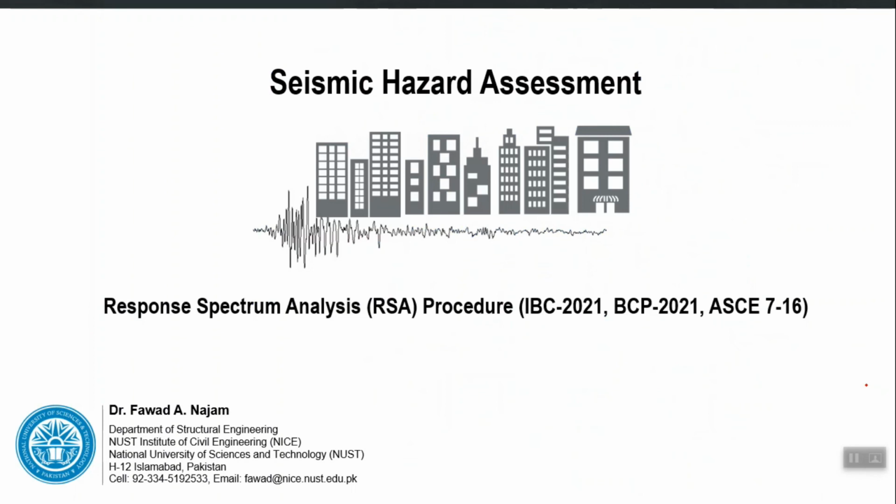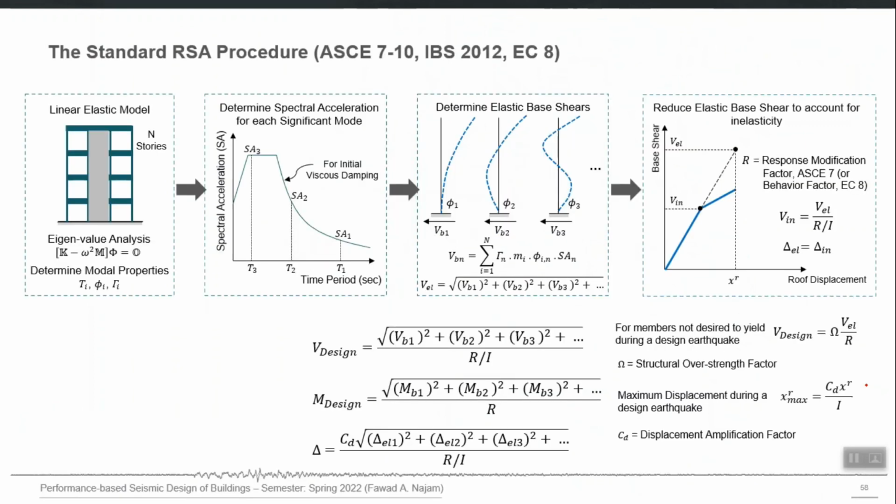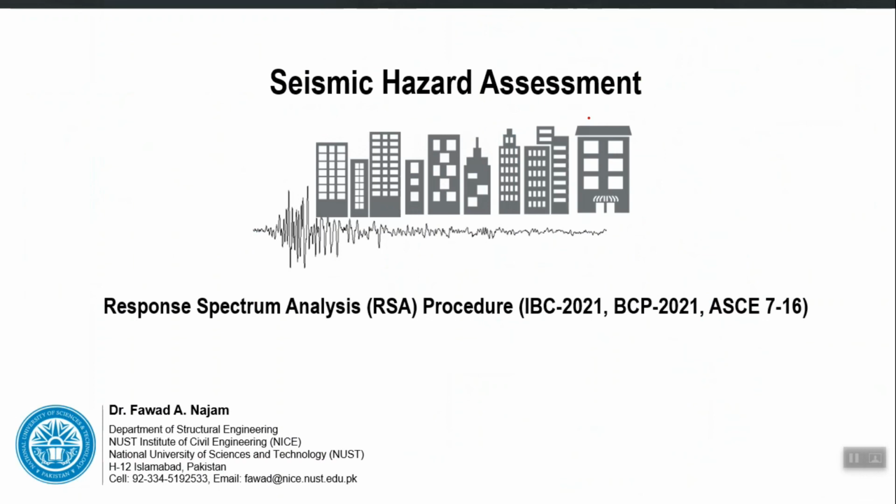So, we were discussing the response spectrum analysis. Actually, let me give you a quick overview of what we are currently discussing. Just a quick recap. We are discussing the code based seismic analysis procedures, which are conventionally used for structural design purpose or structural evaluation purpose, but they are recommended by building codes, which means primarily they are based on the use of linear elastic computer model with some implicit considerations to consider nonlinear effects, right.